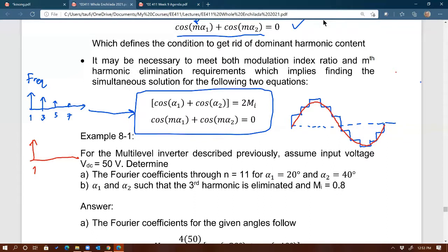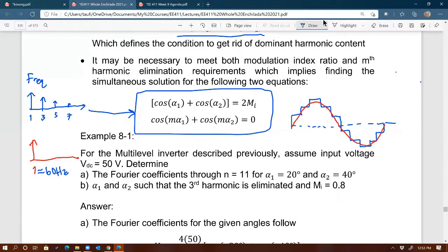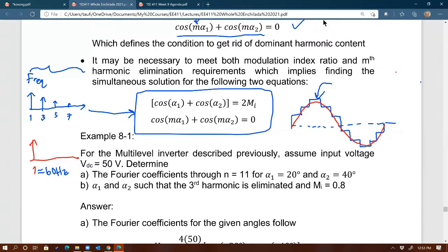Yeah, the sine wave is a pure sine wave. That means it only has one frequency component, which is at 60 hertz, right? But if you have a square wave, the final square wave, not the individual square wave that you are adding, this is the final square wave after you add them, right? They will have these components. Oh, you're just talking about one of the square pulses, but you're adding multiple together. That's correct. Yeah, this is the final square wave, the final waveform, the blue that I'm drawing right there. Without filtering. Without filtering, yes.